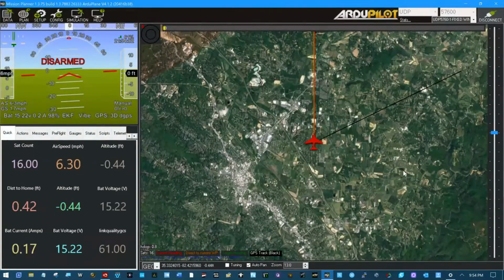You're really going to have a hard time pointing at your platform with your control antenna then. So unless you've got a coax coming out of the top of the Crossfire transmitter going into a ground station with an antenna tracker feeding that antenna and pointing at your platform, setting up high gain antennas, it just gets crazy.